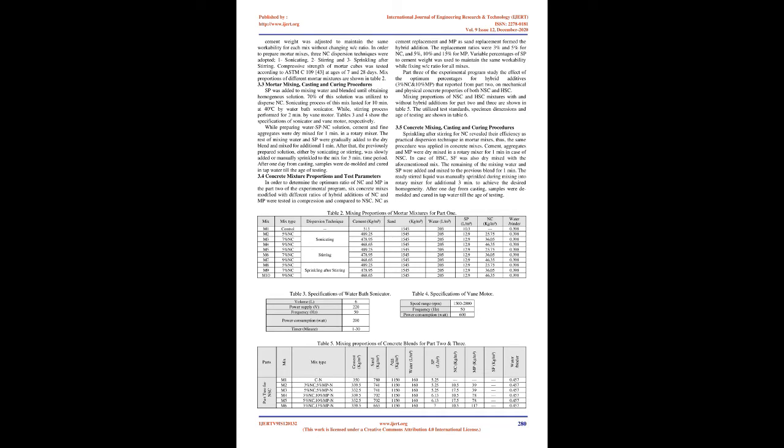Omar et al. 37 found that the use of limestone waste as sand replacement and marble powder as an additive in concrete has more significant effect on the mechanical and permeability properties of concrete. The enhancements were revealed with MP up to 15%. Ahmed et al. 38 recommended that replacing fine aggregates with 85% of crushed rock dust and 15% of MP improved strength and durability of SCC. In addition, the combined effect of replacements revealed a significant enhancement in the segregation resistance.